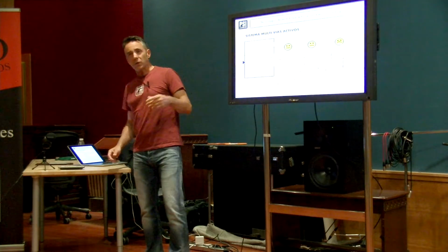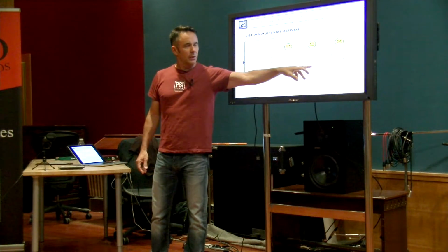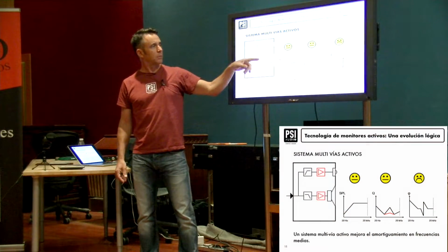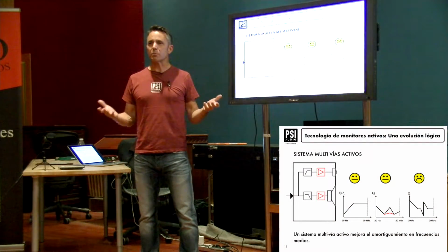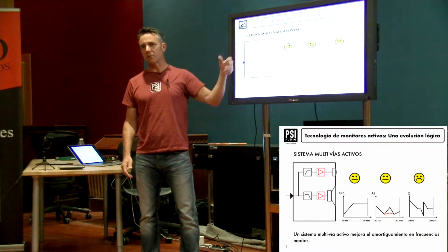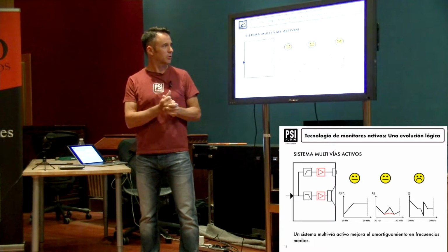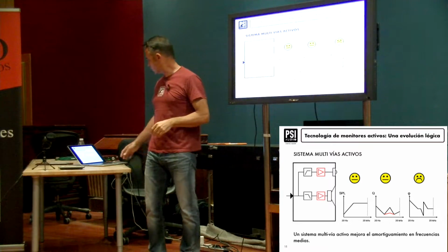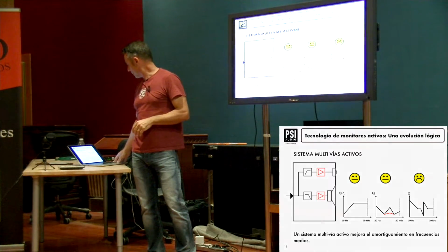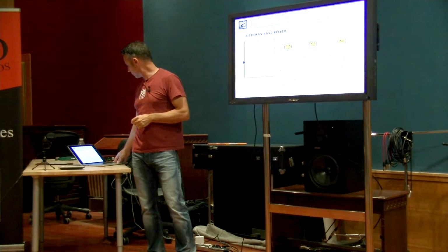Oh, no, sorry. One of the ways of getting less distortion here is to have two amplifiers that each one is perfectly adapted to the membrane it's driving, okay? So that you can have the filters before, and this is what you call an active crossover. Each driver has its own amplifier. That's also the common way of doing things now.